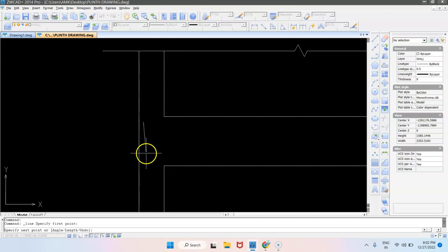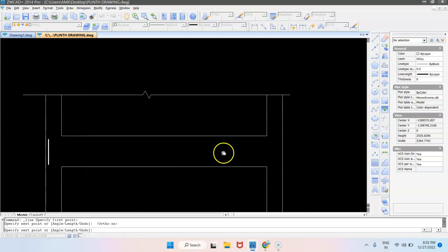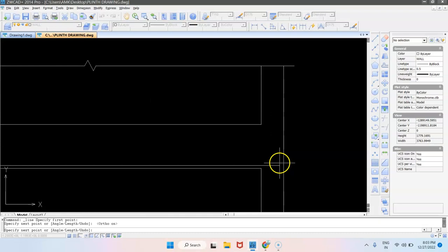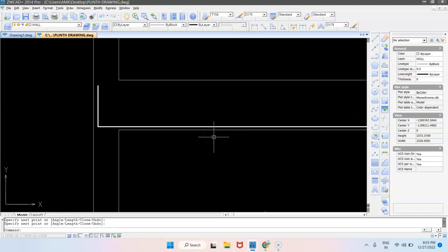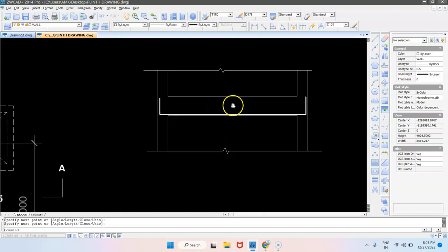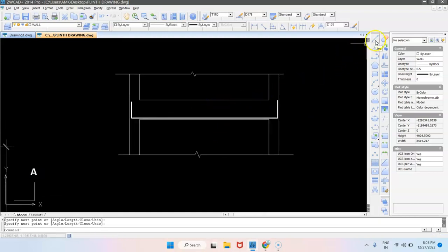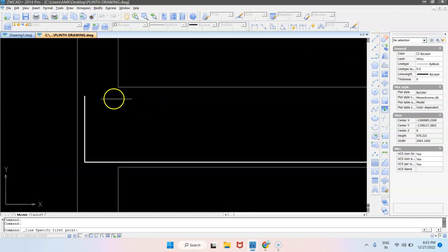Now one important point to note here is that when you are drawing the reinforcement in the beam, the bar is taken up like this, up to its full depth within the column for getting the necessary development length. We also leave a certain distance from the bottom of the beam as a cover. Similarly, you will see that the top bar, which is called the anchor bar, is going to be drawn somewhere here.